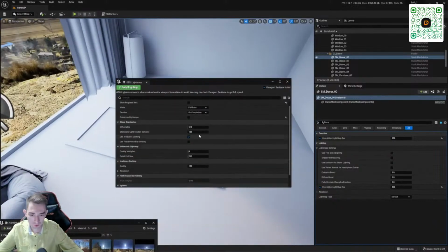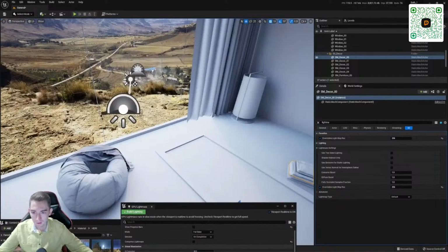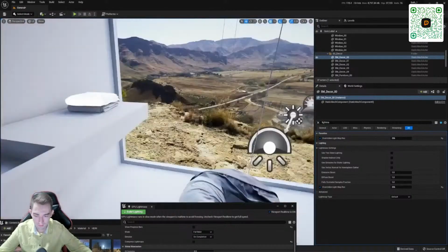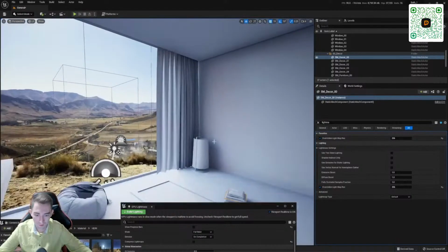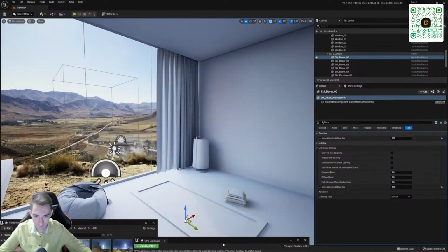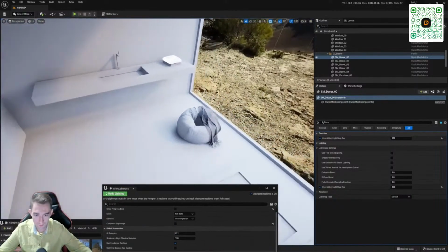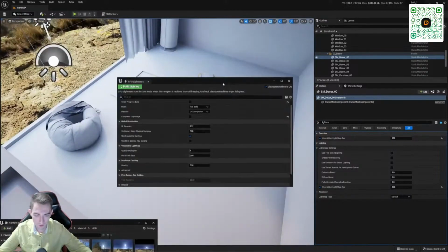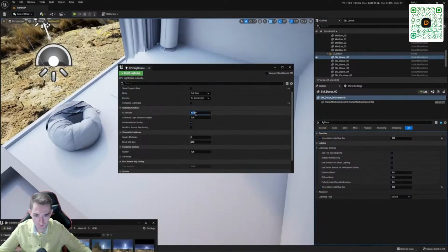I think the quality will improve if the quality of the light map settings is improved. So, I'll try to put a good resolution now. I'll turn it on now. So I'll try to put a good resolution and see how it renders. Let's put it like this. There are 2048 here.